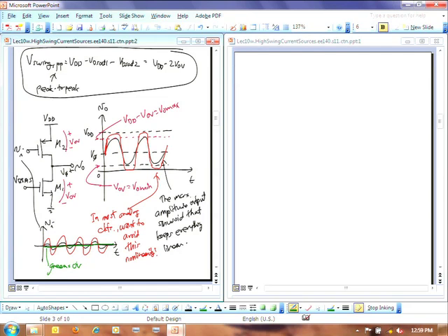Okay, but usually a lot of these analog circuits have to detect things you can't even see on the oscilloscope unless you really make the volts per division very small. Right? If you zoom in on the signal on an oscilloscope, you never see just a nice flat line coming out. You always see this. Some fuzzy signal there, and that's noise.